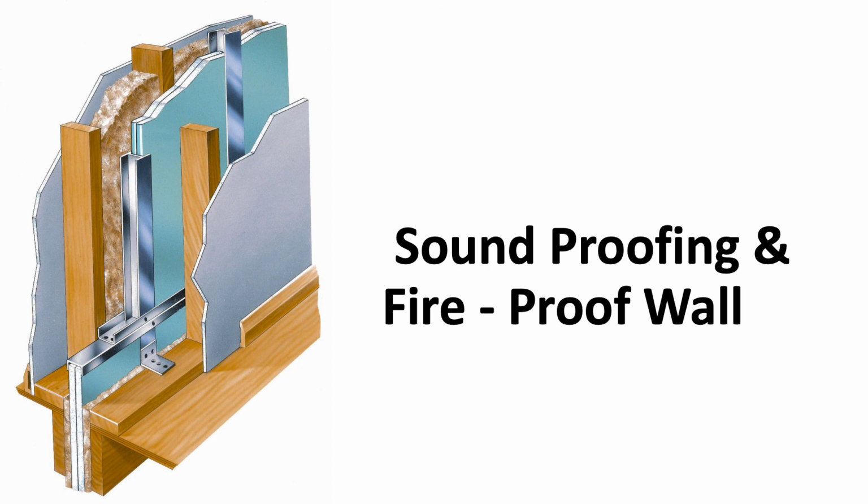Most all of your stairways, if they're not constructed out of concrete block, will have 2 layers of 5/8 sheetrock on them, so you get that 1-hour fire rating on the wall. Some elevator shafts may have as many as 4 layers of sheetrock in low-rise buildings. A lot of low-rise buildings will have sheetrock elevator shafts. When you get into high-rises, they normally are built out of concrete. I have seen some as tall as 8 stories with 4 layers of sheetrock. You get those wet from overhead, and they're really challenging to dry.